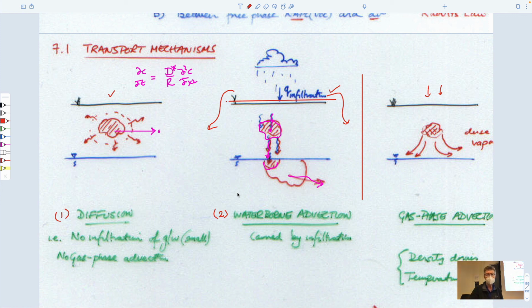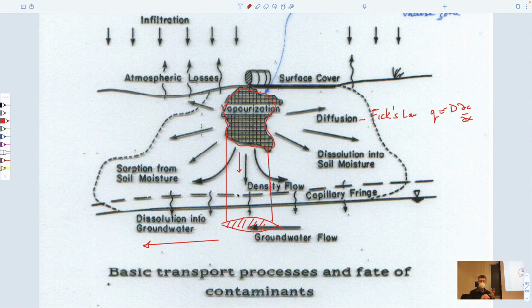So that's it. So we've talked about conservative transport, we've talked about non-conservative transport, both in the groundwater saturated zone. Those are 3 and 4. And we finally closed it out by talking about transport within the vadose zone and looking at both conservative and non-conservative transport by virtue of the fact that we've talked about retardation. We talked about how to define retardation. We've talked about the importance of advection in increasing those magnitudes. So now, since we've talked about all the transport mechanisms, I guess we've laid the ground rules to be able to say, 1, how stuff gets in there, 2, how stuff migrates, we know that, and now 3, how we can use our knowledge of these mechanisms to maybe remediate these systems.